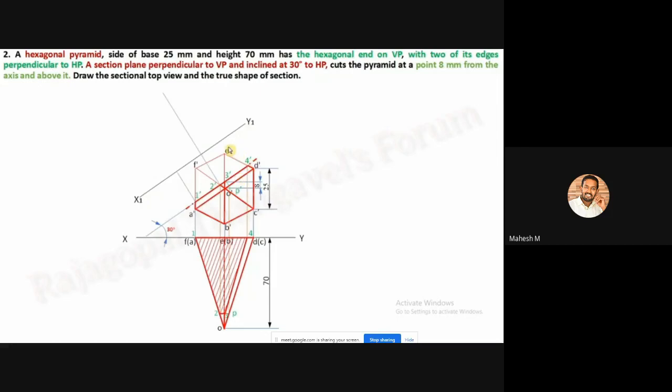Then you can project all the cutting points towards the imaginary reference line. So 1 and 4 are available on the reference line. So this one is 1 and this one is 4. 2 and 3 are far away from the reference line. So you can measure this vertical distance. Then you can mark the distance exactly at this point towards this and this point towards this. Okay, so 1 dash, 2 dash, 3 dash and 4 dash. You can join these 4 points with a dark line, then you can create the section lines. Okay, so that's all about the final diagram.